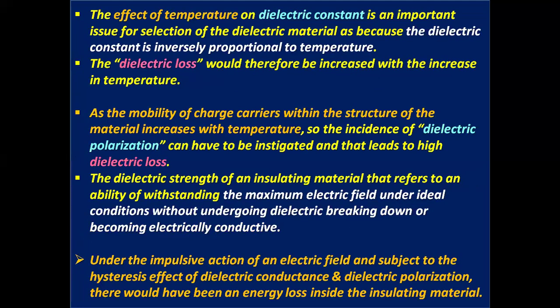The effect of temperature on dielectric constant is an important issue for the selection of the dielectric material, because the dielectric constant is inversely proportional to the temperature. The dielectric loss would therefore increase with the increase in temperature.